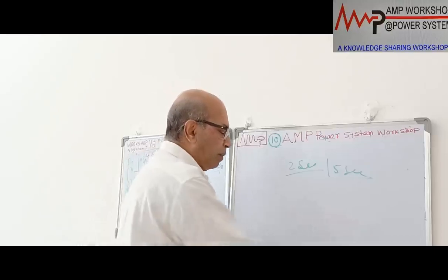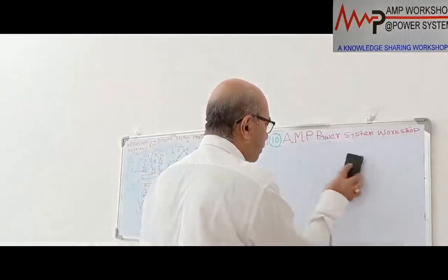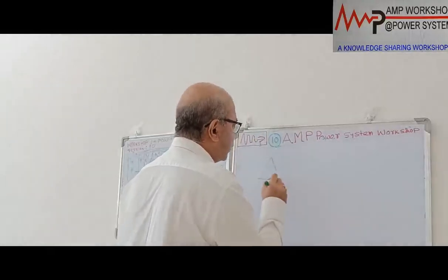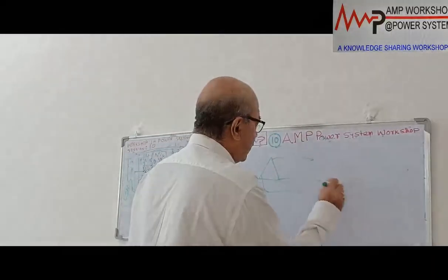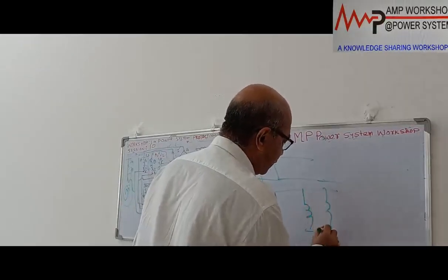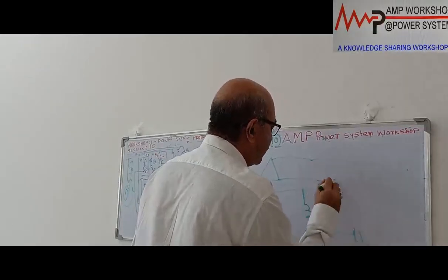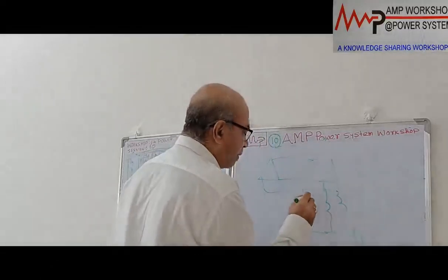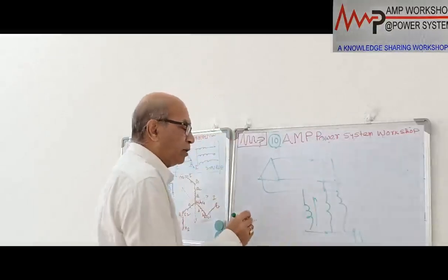Now if we see the kVA capacity of this transformer, this grounding transformer is connected with the delta winding. Suppose this is a delta winding, and the grounding transformer is connected over here and is neutrally shorted. These are the 3 phases shorted. So if you see this grounding transformer per phase voltage, how much will the phase voltage be?